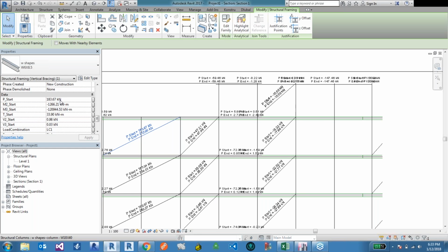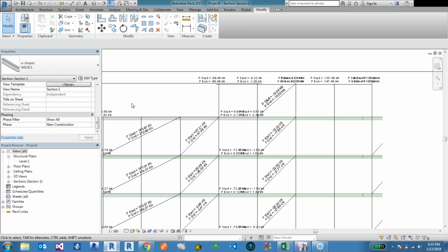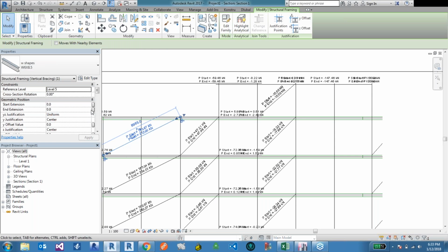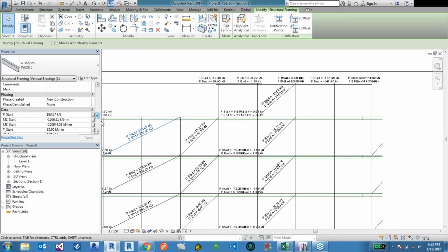I think it depends on the Revit family that you use, right? I think if you have a Revit family set up that has a certain parameter name, I think that's probably the question, whether you can override parameters that are existing in a Revit family. But essentially, okay. If we had a Revit family and we had a parameter called my company's M2 start, we could use Excel, for example, to map all the values from our M2 start into my custom M2 start parameter, kind of similar to what Max just showed by adding a custom parameter. Yeah, that's right.